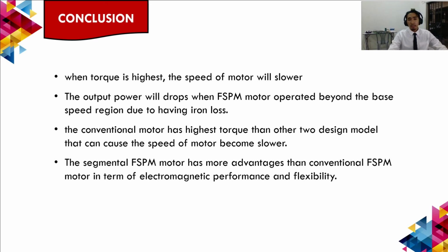For example, if the stator core in the conventional motor is broken down, the motor cannot run. But with the segmented stator, if one of the stator cores is broken down, the other segments will still run.